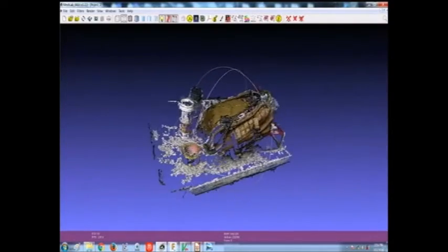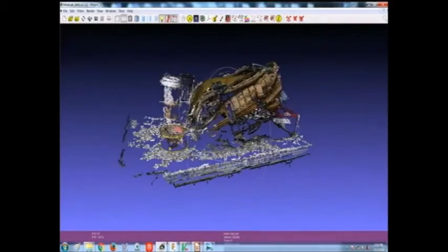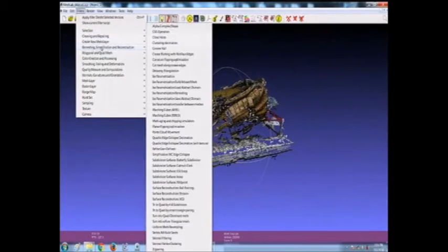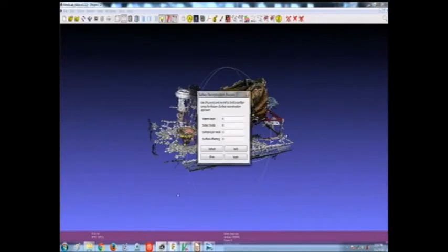Now, this is the dense point cloud, right? We look in here and we can see all the little tiny points floating around, but nothing stitching everything together. We need to run a process to stitch everything together, and you find that in some of Meshlab's filters. The one I use 99% of the time is in the remeshing option here, and it's called Surface Reconstruction Poisson, right there. So magic numbers, the octree depth is 11, the solver divide is 10.